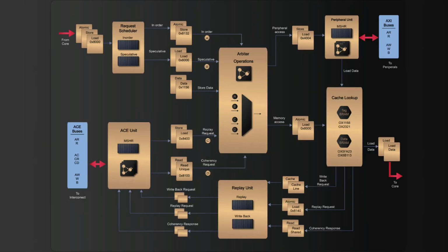We also reworked the memory access unit and data cache. The new data cache is non-blocking, supports cache coherence, uses a pseudo-LRU replacement policy, and includes miss status handling registers for handling multiple outstanding memory accesses.